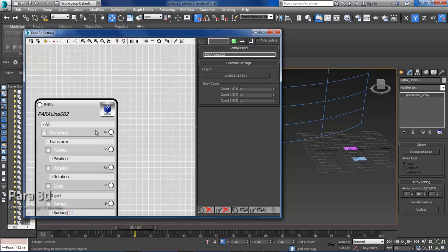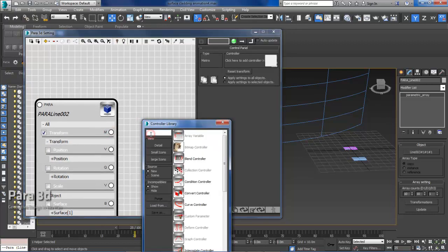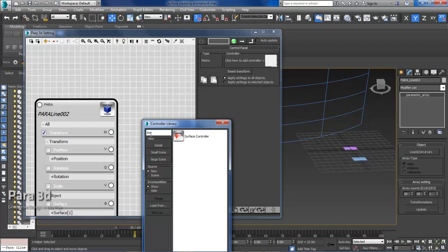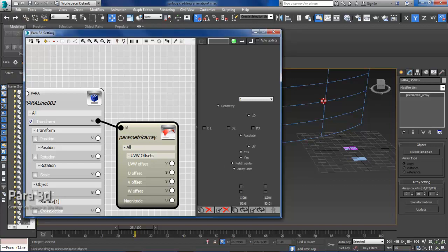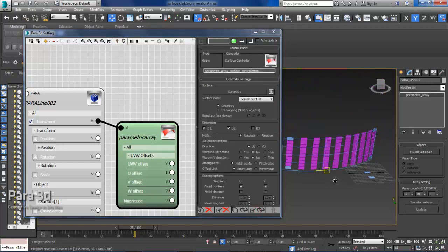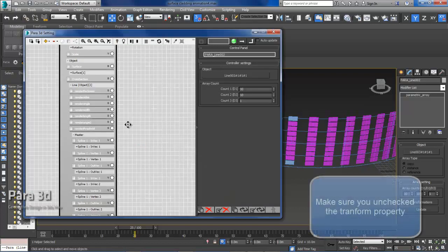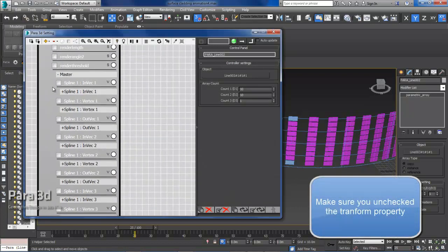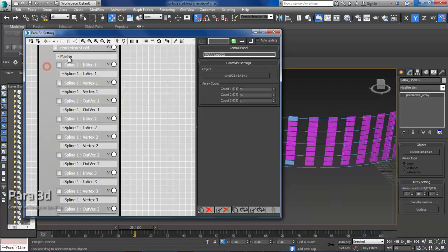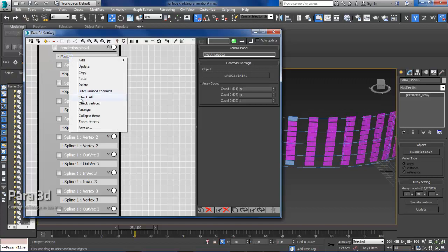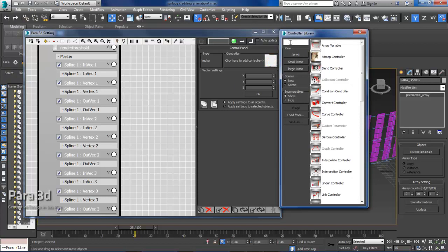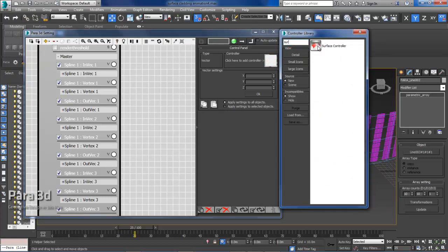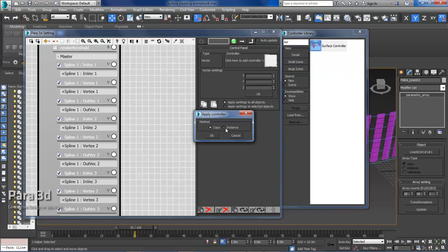Okay, the first thing I'm going to do with this is to put those panels on the surface. It's a good practice. It's always good to do this first. So we go to that and then we put that on top. So now, as a normal surface paneling, like in other tutorials, you go here, click on the master group of properties, and then check all. It's going to select all the control points, and then come here and add a surface controller, and then choose instance.